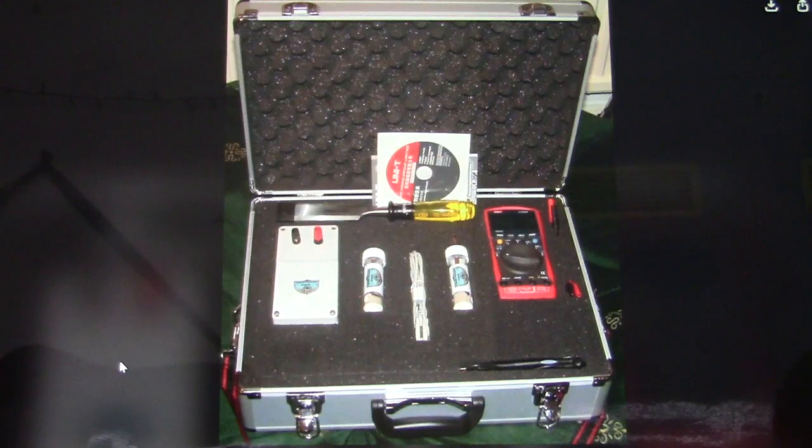The device consists of 4 electrodes, 2 at the top and 2 at the base. One top electrode is cleaned to bright metal, which makes it active, anodic, while the other remains passive, cathodic. When an electrolyte sample bridges these 2 electrodes, a corrosion reaction begins at the bright steel electrode.